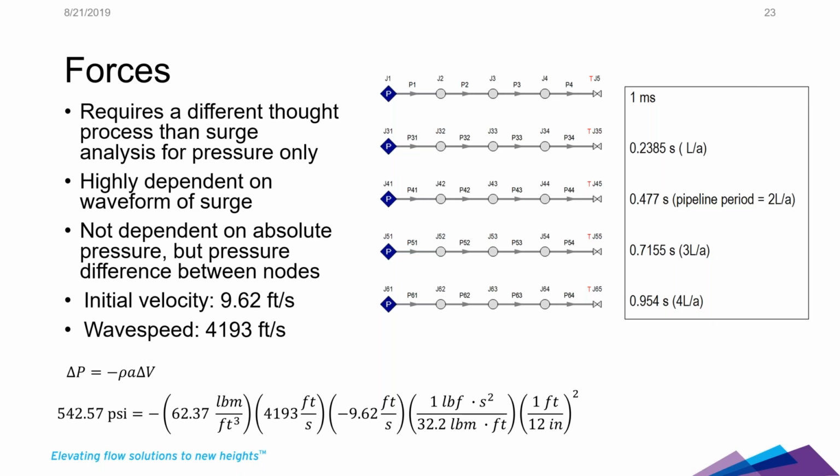Forces are highly dependent on the waveform of the surge, the steepness of your wavefront. When you're looking at animations, it's so helpful whenever you're analyzing forces. I mean, it's extremely helpful when analyzing pressure surges, but for forces, it's critical. So it's not dependent on absolute pressure, but pressure difference between nodes.